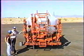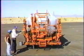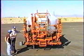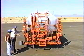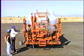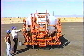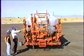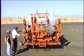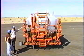All of that adds up to equal spray across the spray bar, and that's why we call these valves equalizer valves, equalizing the feed to all parts of the spray bar. You can see that without that system, if those valves didn't open, the very first thing to get asphalt was the end of the wing over there. So it would shoot the heaviest, and it would get lighter and lighter till you got clear across to here, and this would be the lightest.